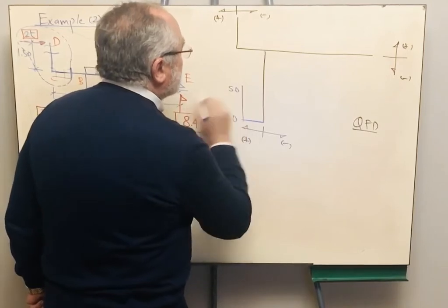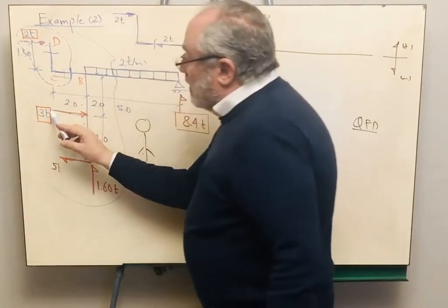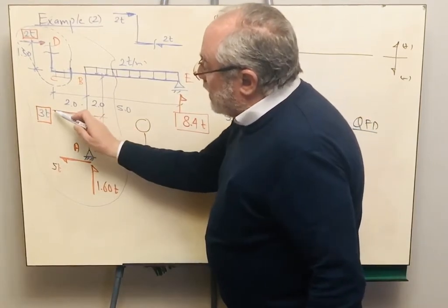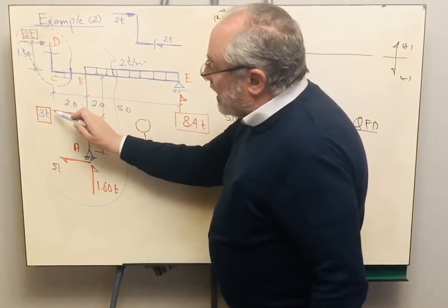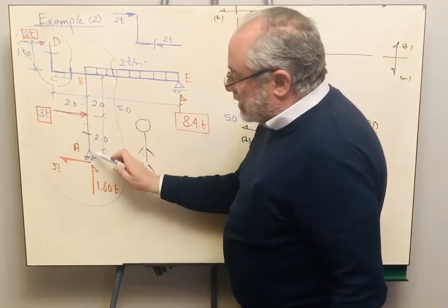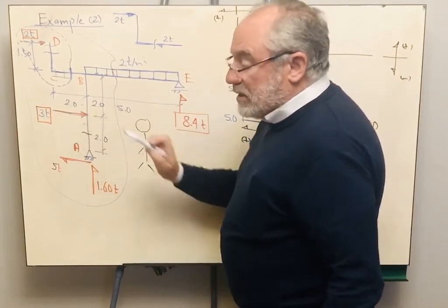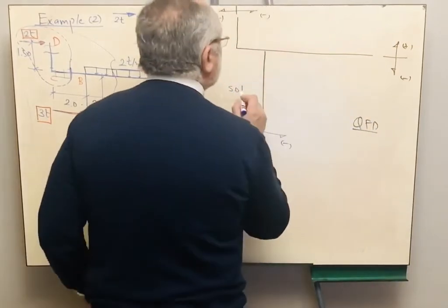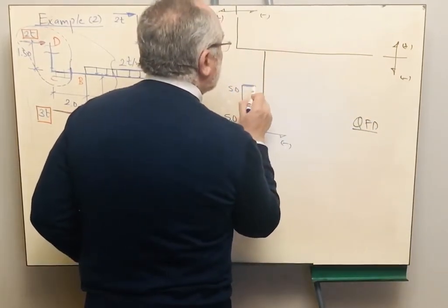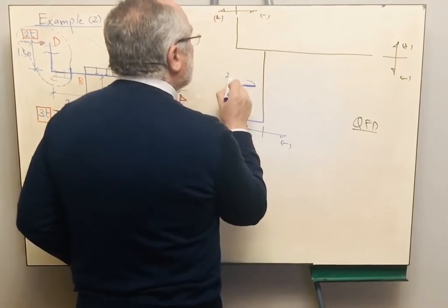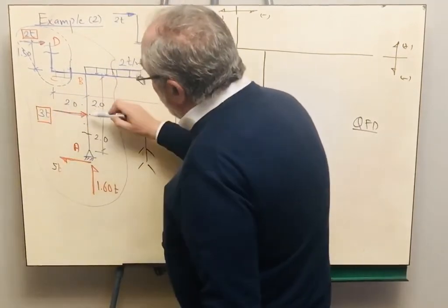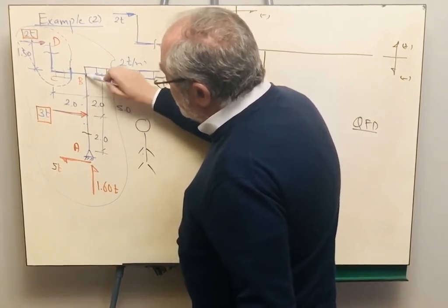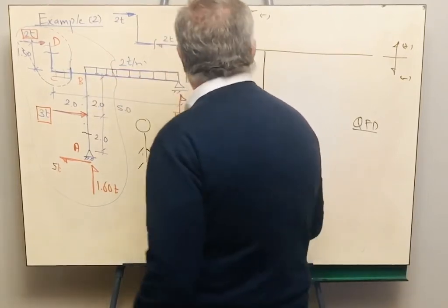And it is 5. Now I am having a sudden, or concentrated, load applied. If you are going to account for this, this is on your left hand side and downward because we are starting from the left. This means that it will cause a sudden reduction in the shear, so it will reduce to 2. This magnitude is 2. From this point to this point, I don't have any forces applied, therefore the shear will persist and its value will be positive 2.